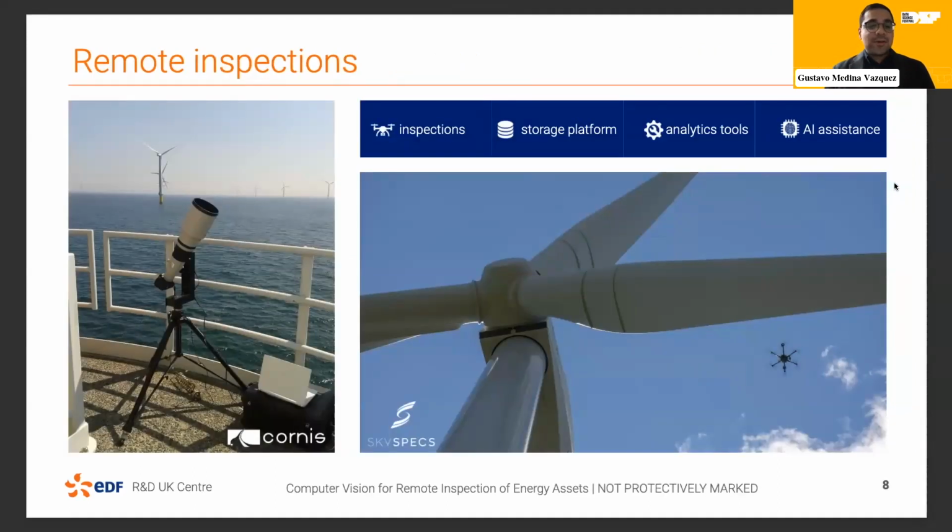Nowadays, we have remote inspections where you would take photographs of the different parts of the blade via different methods. This can be either ground-based photography or by using drone inspections. Here, you remove the risk for the human, and instead you end up with photographs of the blades, which you can then inspect and look for damages.